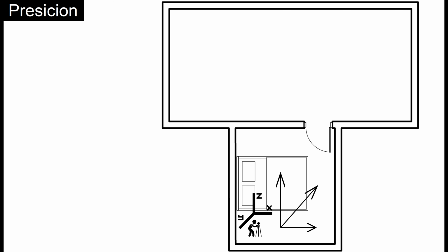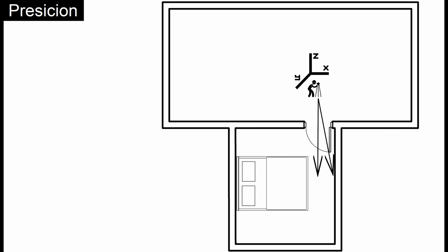By default, the reference point is set to 0, so to update it, I had to calculate an offset based on the reference walls. To do this, I'm picking points on existing walls, but when the measured distance exceeded something about 13 feet or more, the readings become inaccurate. As a result, the offset calculations were incorrect, leading to errors in the data. Additionally, there was some dust in the air, which also caused measurement issues. Some dust particles interfered with the ultrasonic signal, disrupting the sound transmission and leading to the corrupted readings.